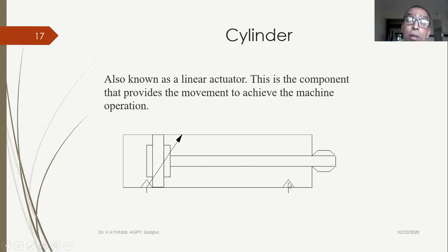It will become supply port. This will become discharge port. What does this arrow mean? This is controlled cushioning effect. So I'll be having one more unit here where I'll be bleeding off some of the air, or some of the hydraulic oil, so that when it reverses back, it does not ram on the body of the cylinder. It will have a cushioning or shock absorbing effect.